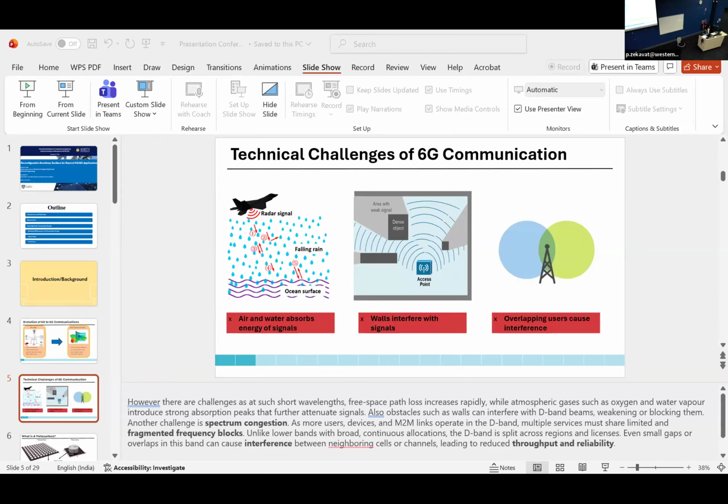So these results confirm that the metasurface has tunable stop band behavior across a 7 gigahertz range in transverse electric polarization, and then a 14 gigahertz range for transverse magnetic polarization, demonstrating a reconfigurable metasurface, which has potential for dynamic suppression of frequencies in both modes in the D-band spectrum.